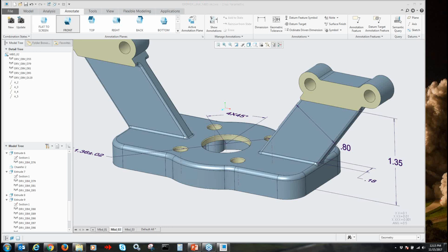So one of the questions here is asking, how much of the dimensioning can be done while creating the model features? So the technique and the way that I've approached this, or my method for doing these now is, as I'm building out my model files, I've set up my start part files to have all the different MBD states and what I'm trying to relay as I'm building out my parts. And what I do is my exercise is after I've created my features out, I'll start going into those MBDs and using my show dimension schemes to go ahead and validate and set up the dimensions, the GD&Ts, my tolerances, and everything else on each specific MBD tab that I may need to.